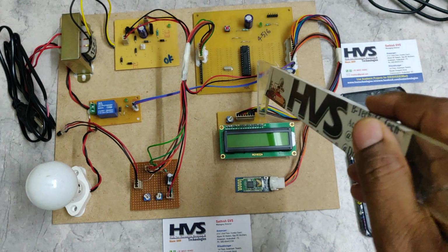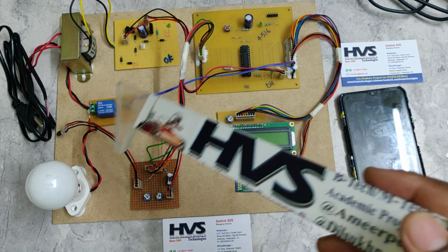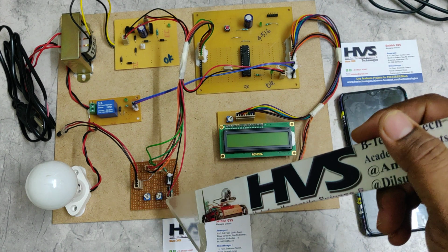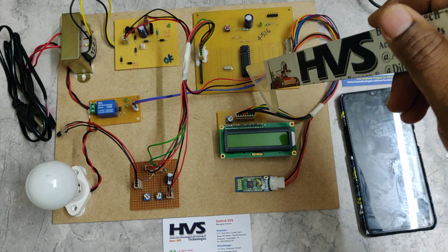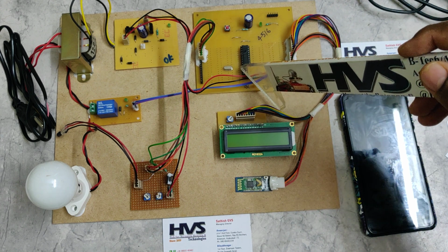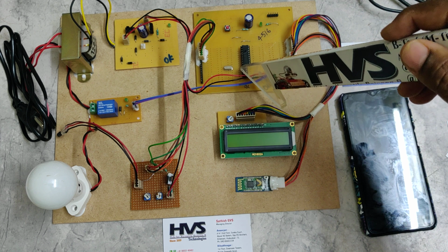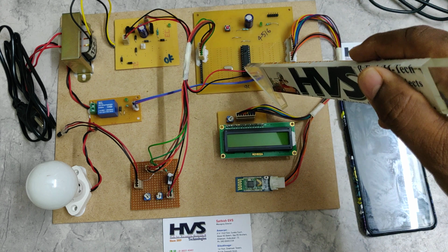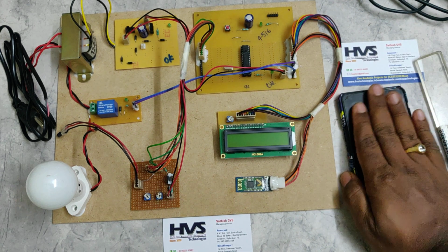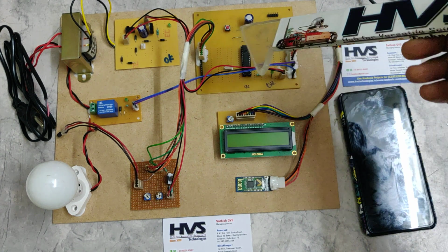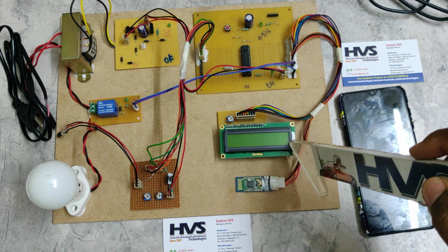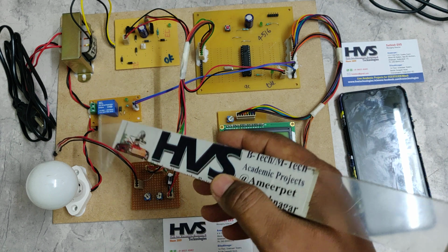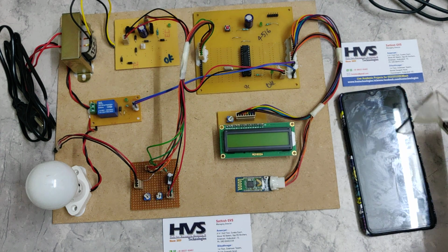Then the microcontroller starts reading the input from the input modules of this measuring sensor board, and based on these input parameters we have to give some instructions based on the threshold values, like low voltage, high voltage, low current, high current, low frequency and high temperature. Based on these abnormalities, it will send alerts to the Android mobile phone through Bluetooth, and the same status will be displayed on the LCD output module, and it will control the load through this electromagnetic relay, which is 5 volt operated. So let us see the demonstration.